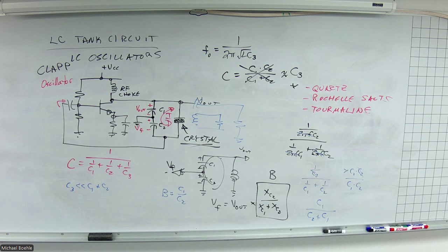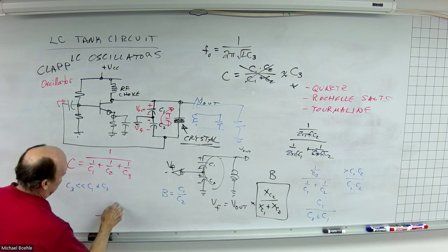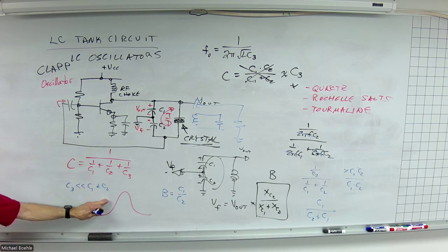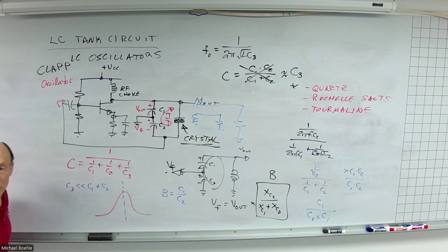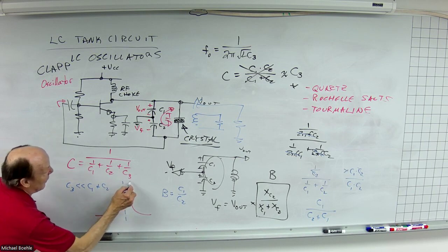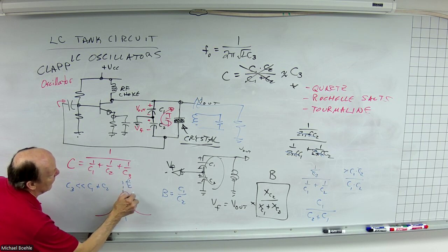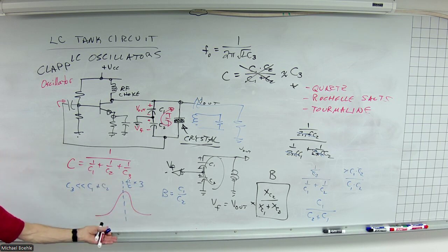And then you introduce some drift with that amplifier. Not as much, because remember, the output of a multiplier is based on the input. Let's say you want to triple it. The resonant frequency, when you do your tank circuit, you're going to get a response like this. But if you have a crystal input that provides a very precise frequency, so whatever the frequency of the crystal is, times 3, that's going to be your output.